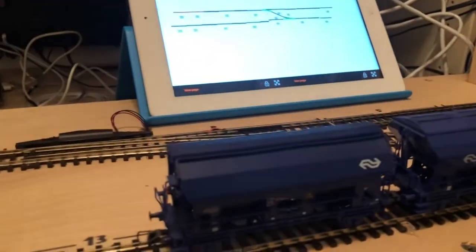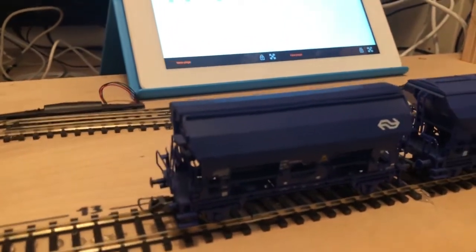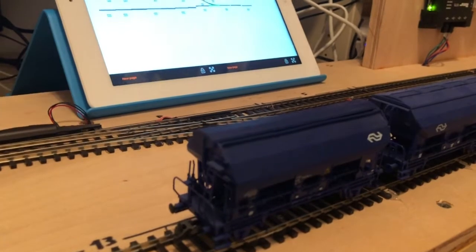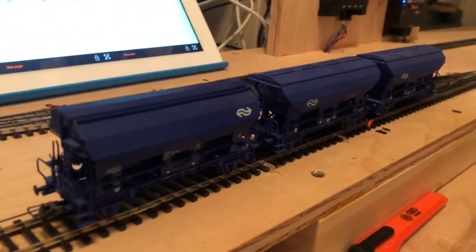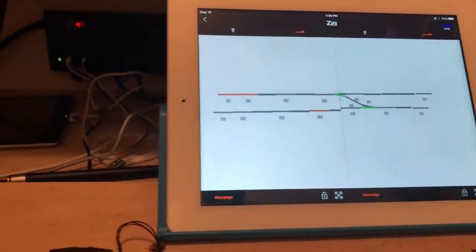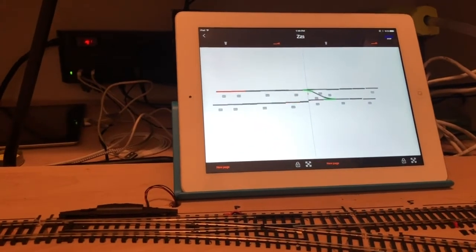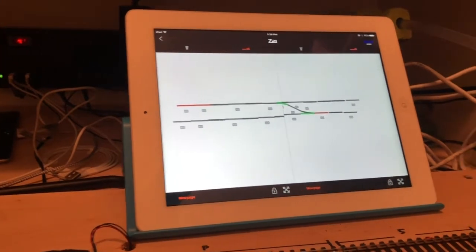After doing some research, I found out that apparently the solution for your carriages is that you would have to put a resistor on at least the front and rear axle of a train composition, or the front and rear axle of every one of your carriages and wagons. So while the DCC sees the locomotive standing there, as soon as the locomotive leaves that track, the carriages are of no concern and it doesn't detect them.